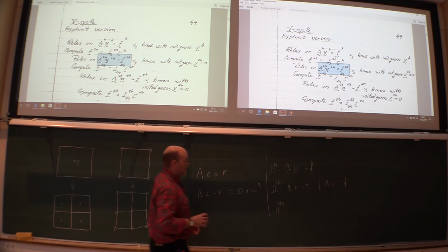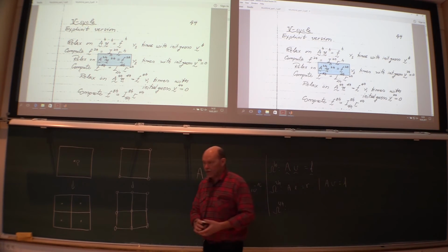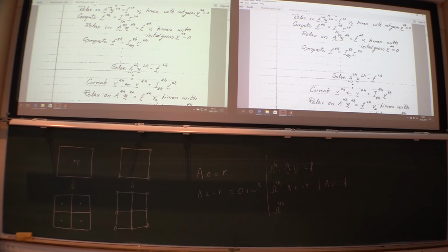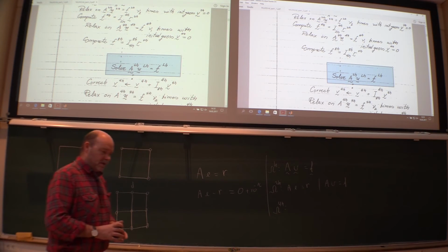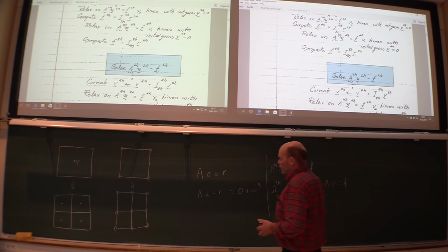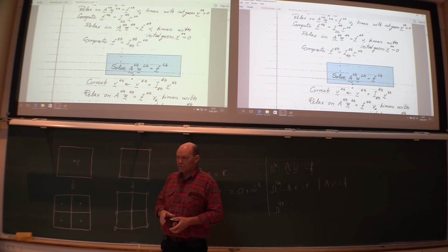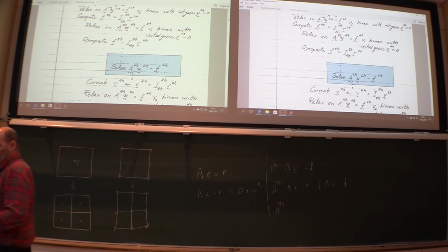Now we are talking about this equation, which is actually the residual equation. Initial guess 0 for the unknown down there, since it is the residual equation. Smart initial guess. And so you continue to coarser and coarser mesh all the way down to the coarsest mesh possible. There you solve the equation. Somewhere along the line you need a solution, of course you do that on the coarsest mesh. If you're lucky, you have such a coarse mesh that you are down to one single unknown, which is just solved directly. But that depends on your geometry, if that's possible, of course.